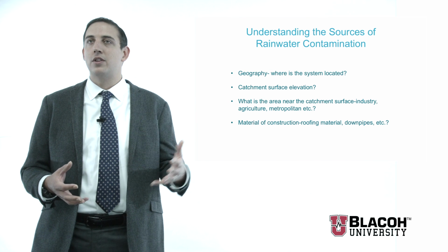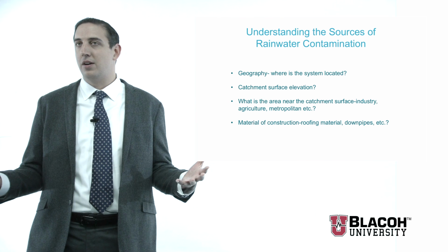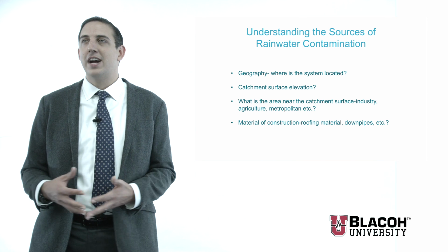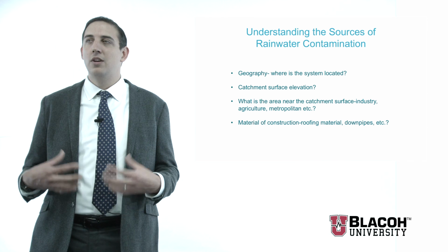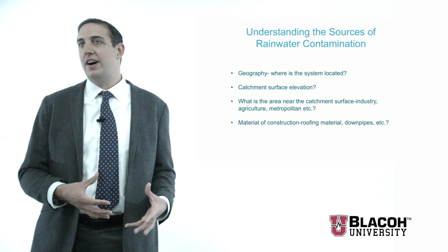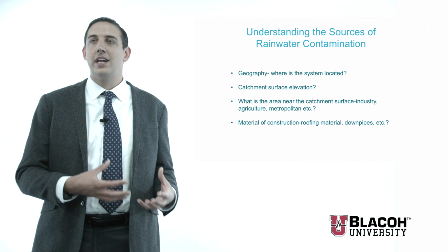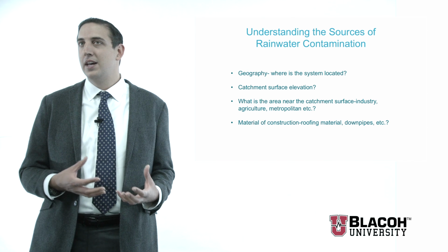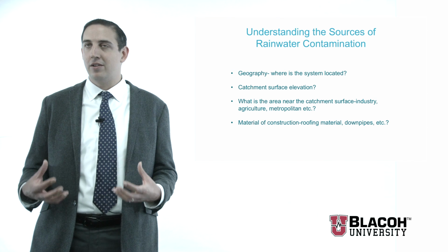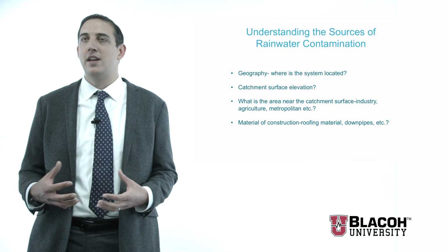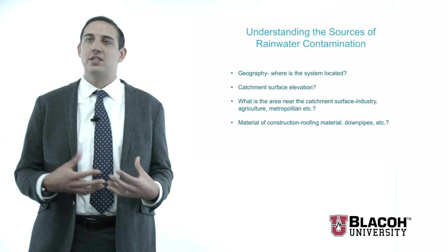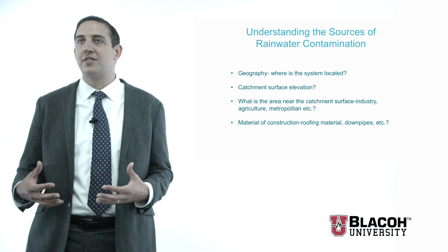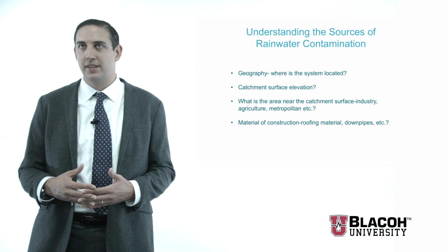As I said earlier, in the Northeast, we predominantly have acidic rainfall. That's a universal. We never have basic rain, we always have acidic rain. As a result of that, any water we collect is a very acidic environment. Acidic environments are good areas for bacteria to grow. They also will cause a lot of metals to dissolve. Most transition metals, which is what you find, leads and zincs and coppers, all dissolve under acidic conditions because they themselves are actually metallic acids.